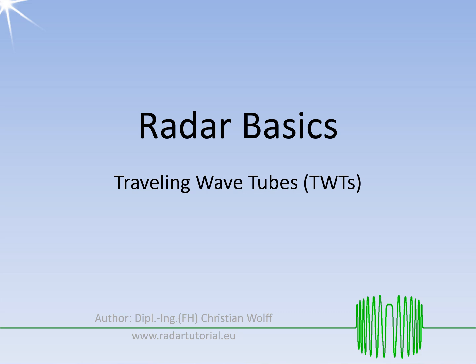This video describes the design and basic operation of traveling wave tubes. Traveling wave tubes, abbreviated to TWT, are vacuum tubes used as high-gain, low-noise, wide-bandwidth microwave amplifiers. In older literature, TWTs are called O-type microwave tubes. These are linear beam tubes. This means the magnetic field is in parallel with the DC electric field.